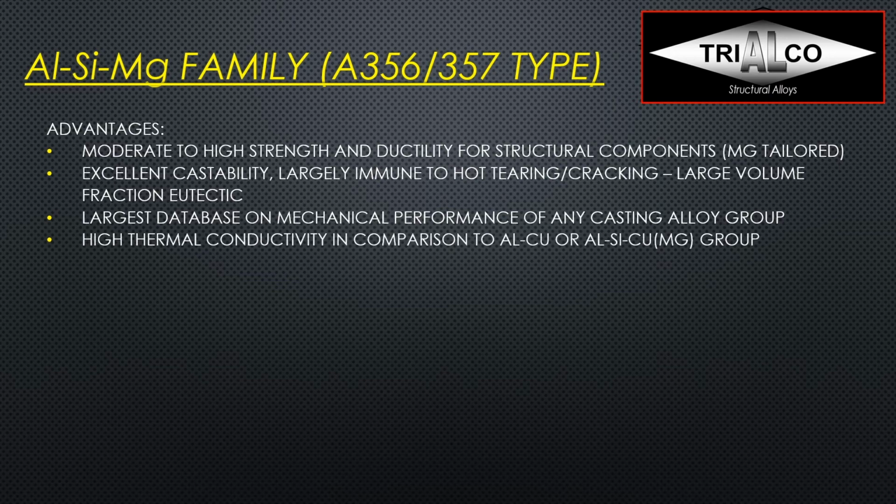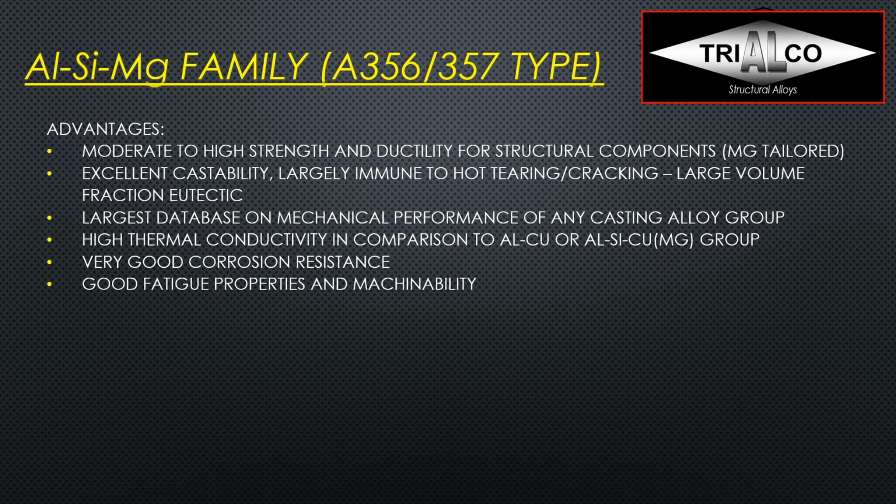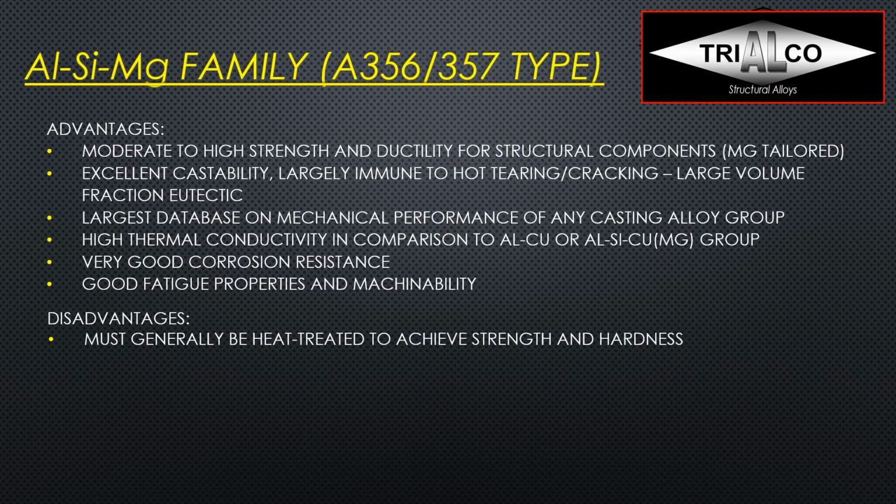So it makes it very easy for a product designer to use one of those alloy types to design their parts. They also have high thermal conductivity in comparison to the aluminum copper or aluminum silicon copper alloy. That makes it very attractive for certain applications as well. And they have very good corrosion resistance because they have no copper in there, or very low. It's just an impurity. They have good fatigue properties and machinability, but their disadvantages are they must generally be heat treated to achieve high strength and hardness.